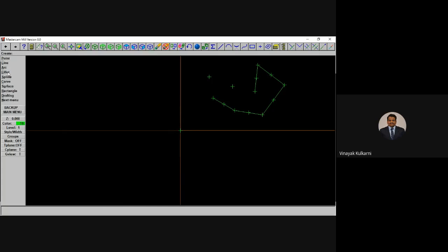Then you have something on line. In line, if I click horizontal and click the first point here, even if I try to make a vertical line, it will never allow me. It will ask me the length. I can either type the coordinate for it, or just click here and it will generate the y coordinate by itself. Press enter, it has created one horizontal line.